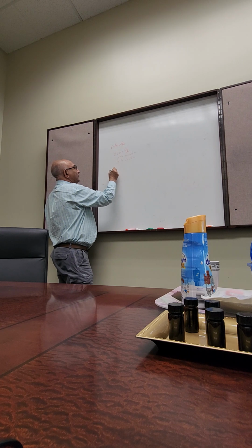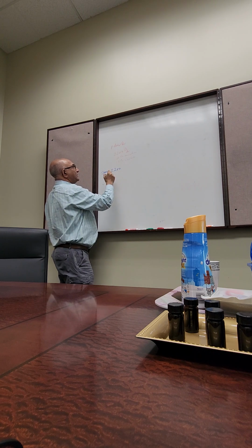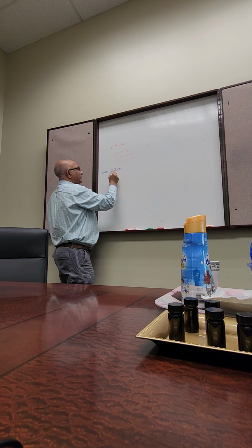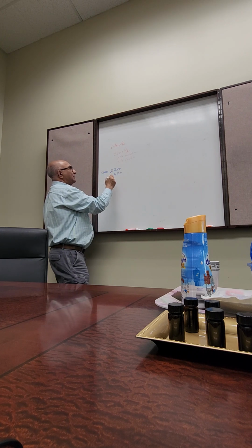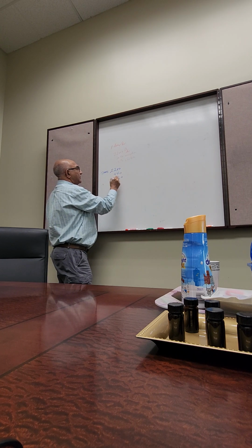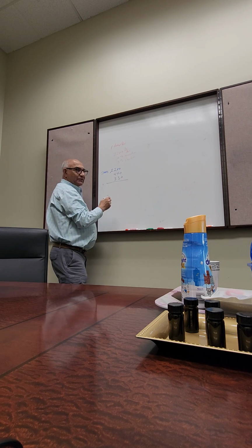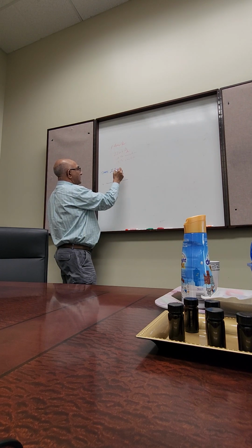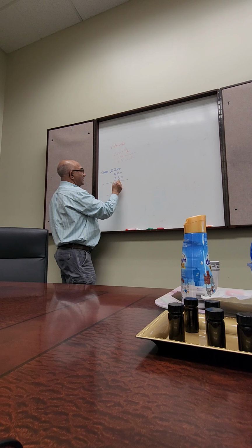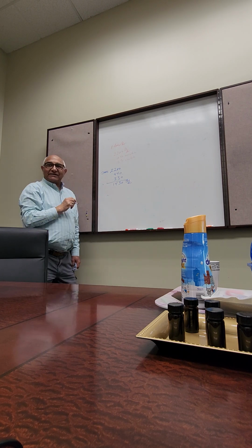So we have 2,200 pounds. That's mass, right? Total mass. And then we have 20%, which is 440, which is water. And 15% is what, 330? So if I subtract all of these from 2,200, I get 1430 pounds per hour that is going to turn into gas.